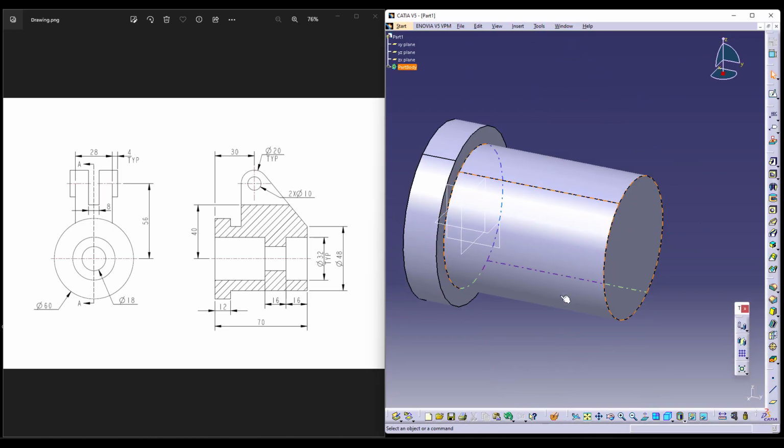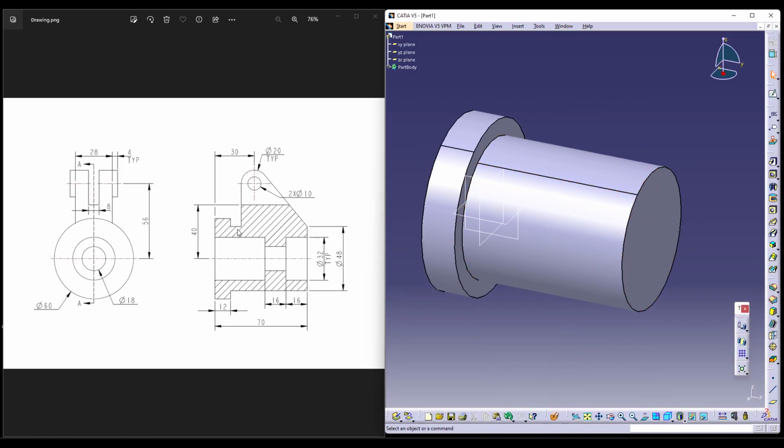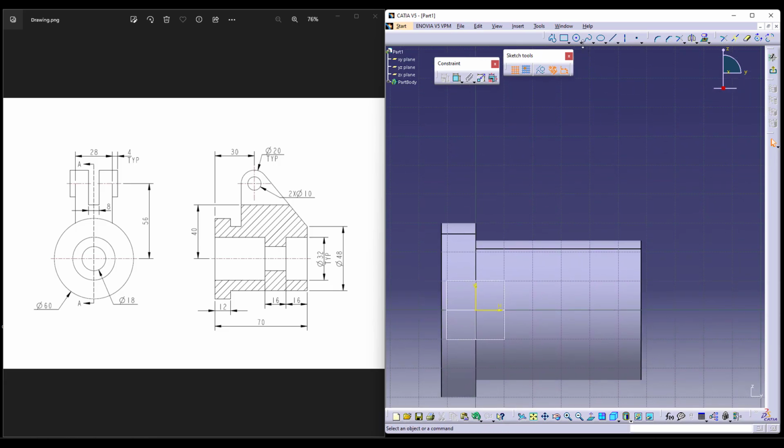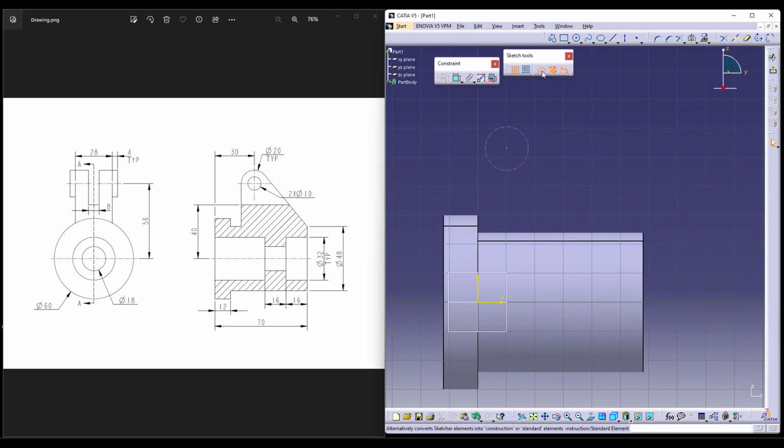It removes the material. Now, the cut you're trying to see is up to this center, that is the end of this circle. So first I'd like to take the references before proceeding, because I don't know the depth of the cut provided here to make this shape. So as a reference, I'll be taking my sketches with respect to 30 and 56. I can use this as the reference for the further modeling.